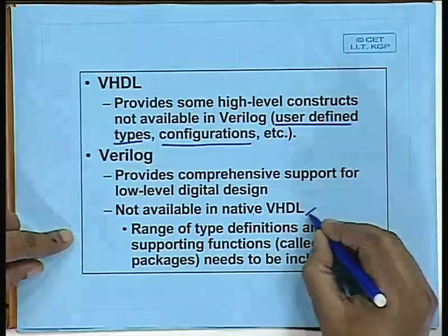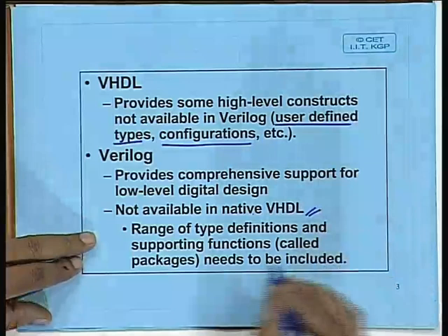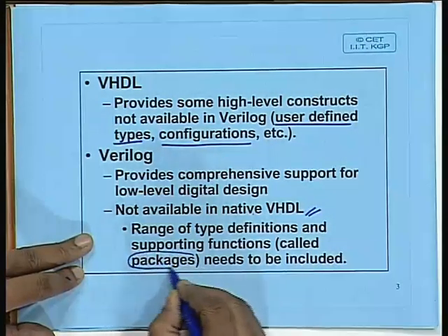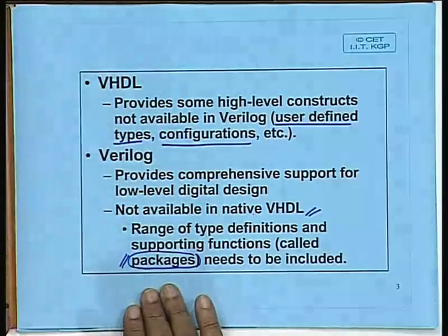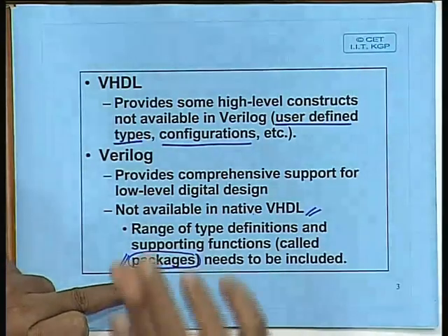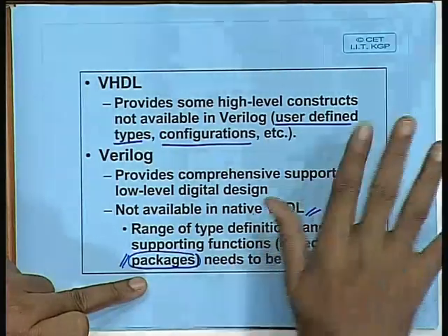Now, in VHDL, if you want to do this, you cannot do it straight away. You will have to import or include something called packages. Packages are something which someone has already written and designed for you. Packages are basically a set of modules where the behavior of all the low level functionalities have been specified to the threadbare detail.